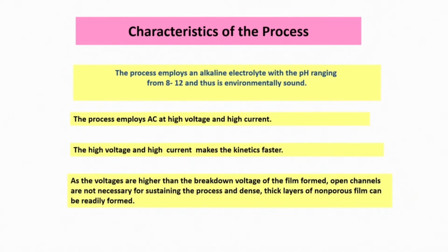If you see the cross section carefully, there will not be a monolithic oxide scale, but rather a composite or cermet scale, where a pure aluminum, titanium or magnesium channel lies in between two oxide channels.